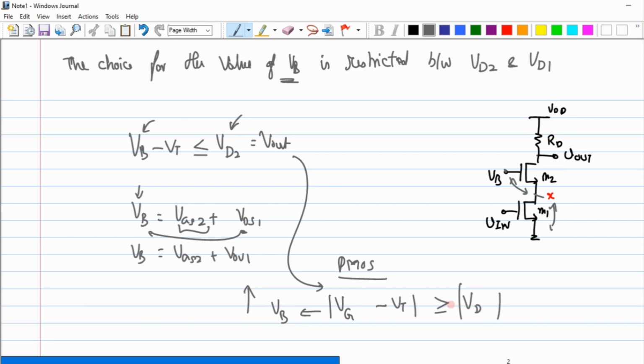Yeah, so if I could replace one of the transistors, then everything could be done. Now, as you said, I could replace M2 with a PMOS, but I will begin by replacing M1 with a PMOS. Okay, I'll retain the transistor M2 as it is, as an NMOS. Now, that type of configuration we call a folded cascode.